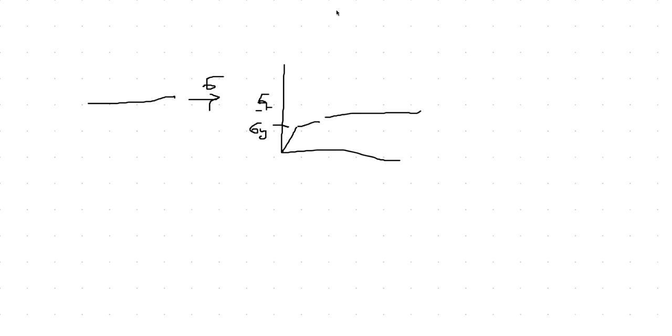If I have, let's say, a bar, and I'm loading this with a σ, and my behavior would be described, let's say up to here, σ_y, and then σ_f. And after that, I keep having some kind of nonlinear response. So I have to define the parameters, which are Young's modulus, then σ_y and σ_f, when these start yielding and damaging.